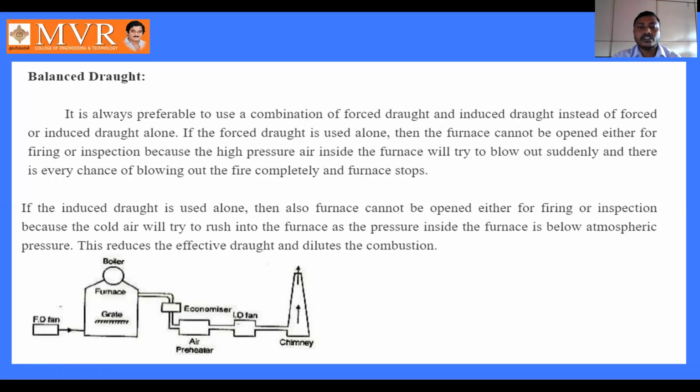So we have two disadvantages: with forced draft alone, the high pressure air will try to blow out suddenly; with induced draft alone, cold air rushes in, reducing the effective draft and diluting the combustion process.